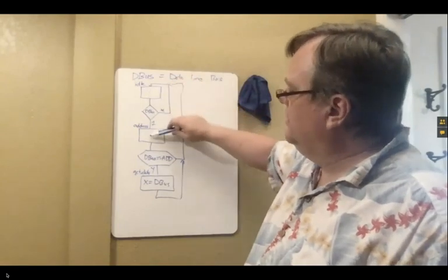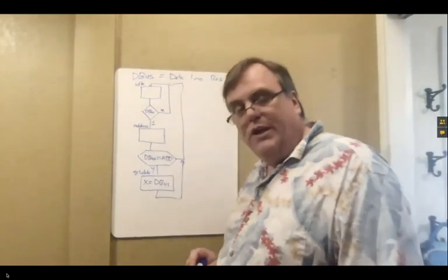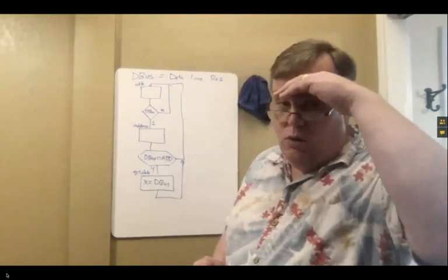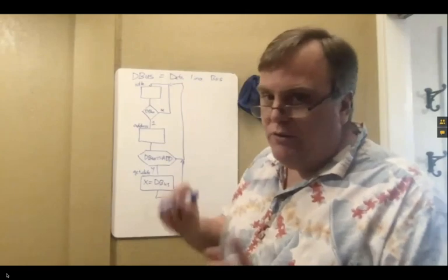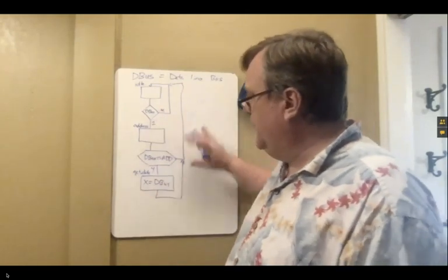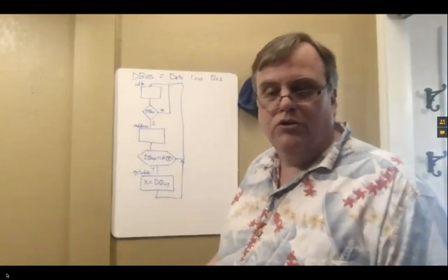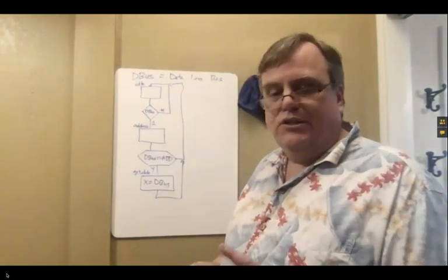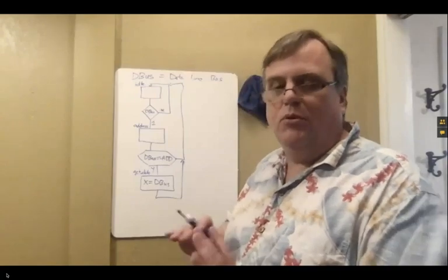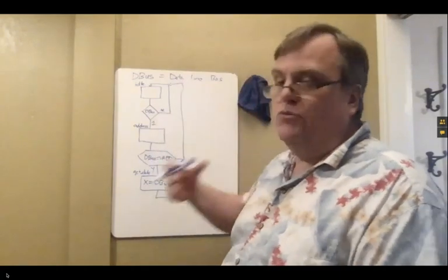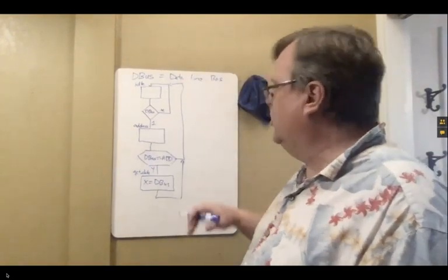Now, I've got three different states. So I look at this and I go, three different states. Now I can pick what matters to me for my addressing style. You have to do everything we've done before, because converting from this is exactly equivalent to all the other things we've built. Right? So the state diagrams, the logic diagrams, state tables, all the rest of that, ASMs are also equivalent. So we just have to convert from this to those.